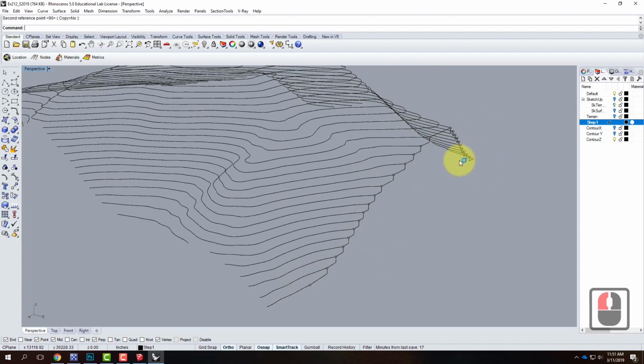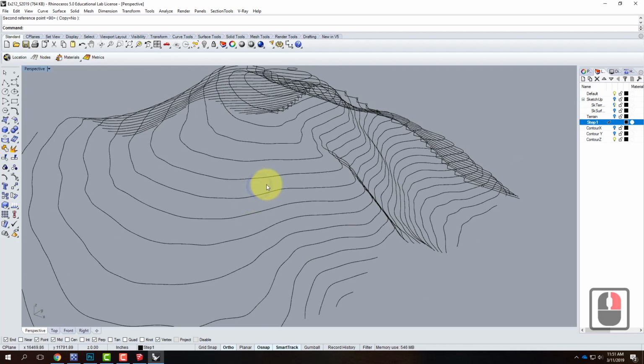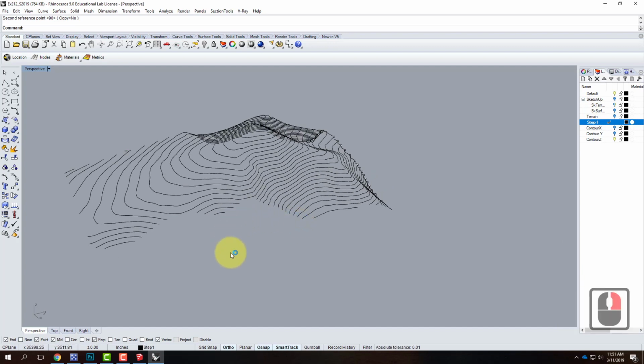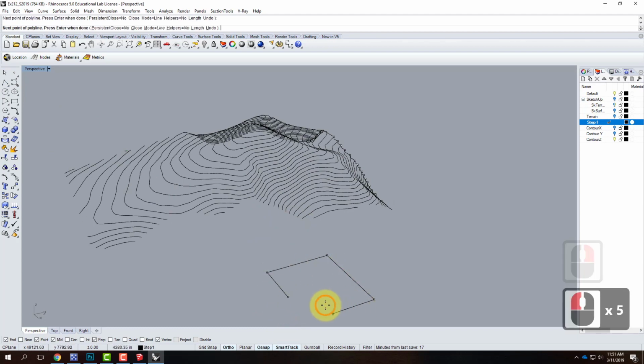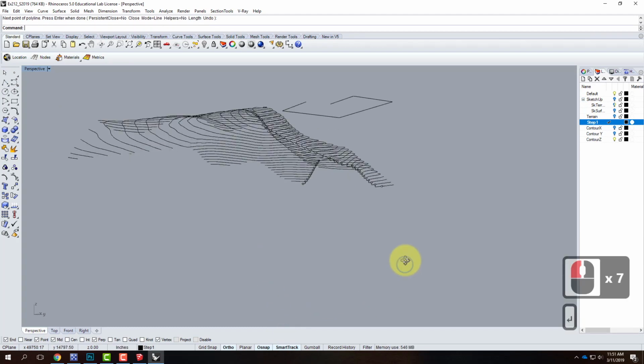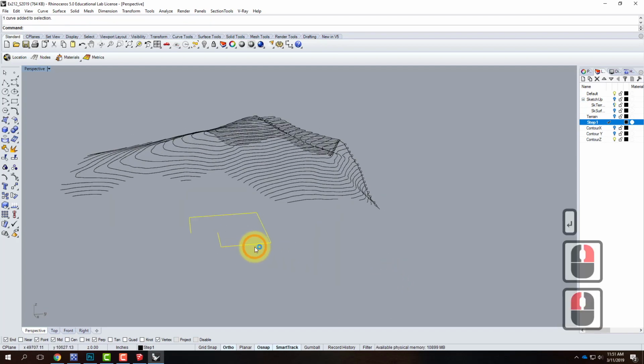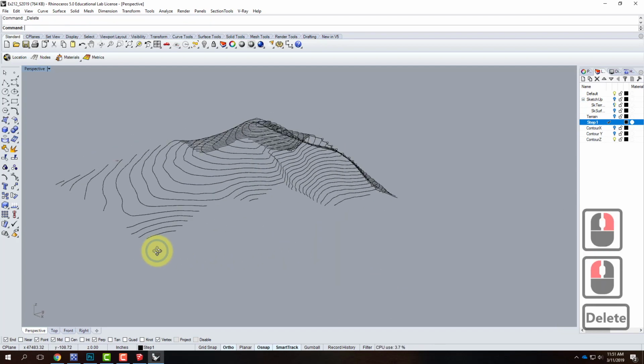The other method is going to introduce a concept called a C-plane, or a drawing plane. It's kind of like the UCS coordinates in AutoCAD, if you're familiar with those. And that is that instead of drawing, so like right now, if I were to draw, everything that I draw is going to be flat on the ground. So it's always going to be flat. Instead of drawing in that context, I want to draw so that it's vertical. I want to choose what plane I'm drawing in.